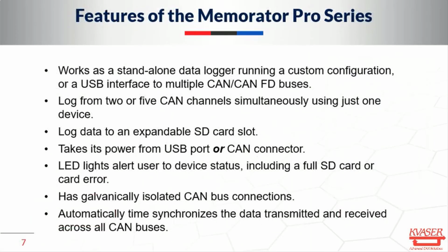Features of the Memorator Pro series, the two products in that series: they work as standalone data loggers running a custom configuration provided by Memorator Configuration Tools, of course. They also act, I want to stress, as a standard USB interface, just like any other USB interface from Kvaser. The USB CAN 2X or USB CAN 5X functionality is exactly duplicated in the Memorator Pro series. So they really act as 2 products.